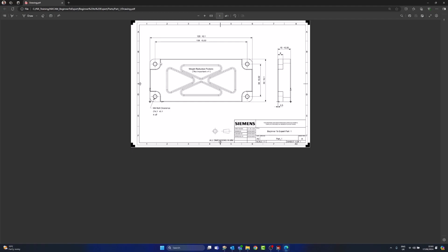So it looks like they're going to have to be done in one operation, or at least on the same operation, because that way we'll achieve the best tolerances. Also, we can see we have a 15mm thickness, and that's tied up to plus or minus 0.5, so that's something to bear in mind too. But really these hole positions are the only complex thing we're going to be looking at, and then this will be a factor for op2.